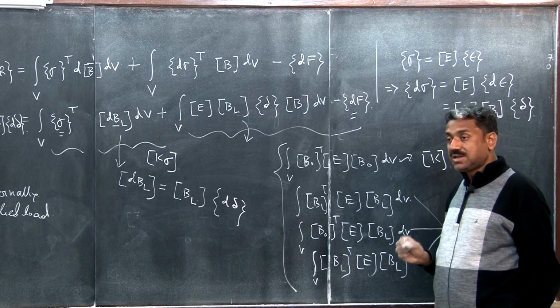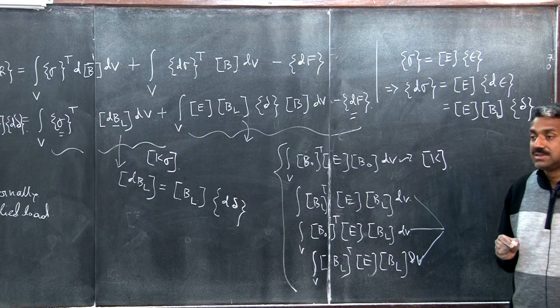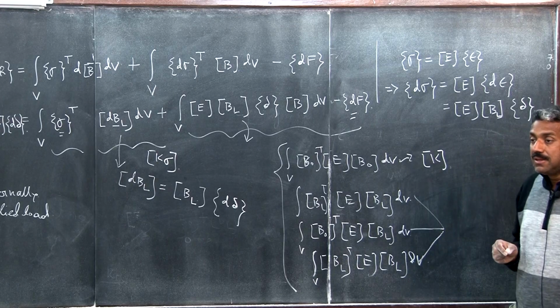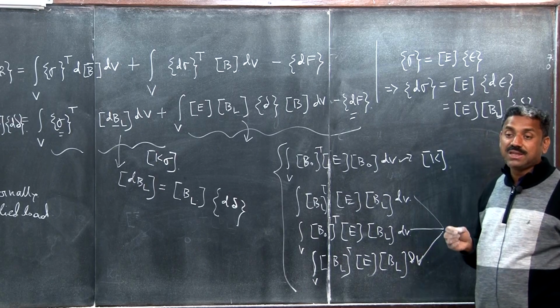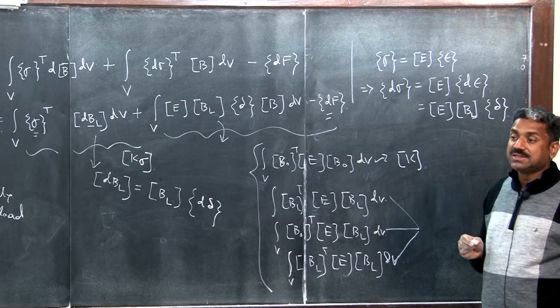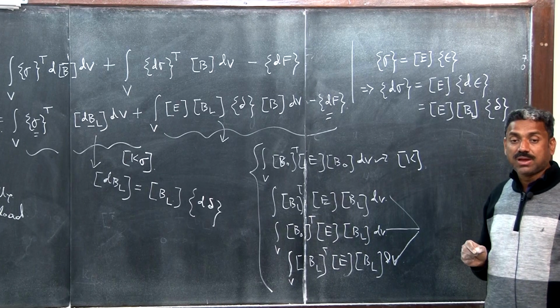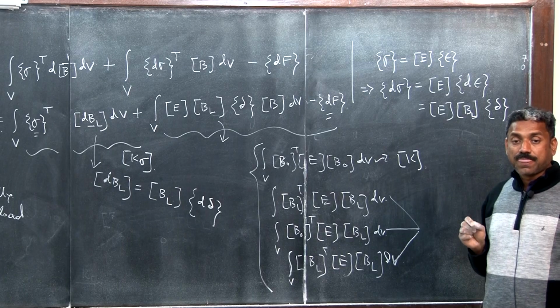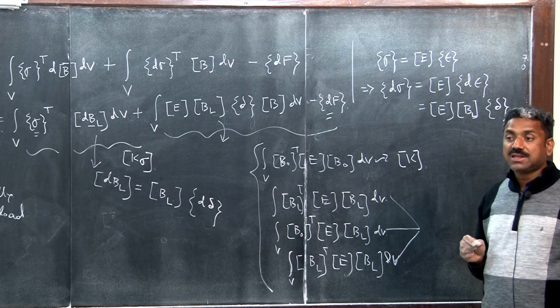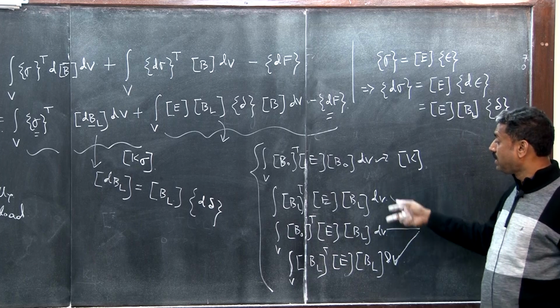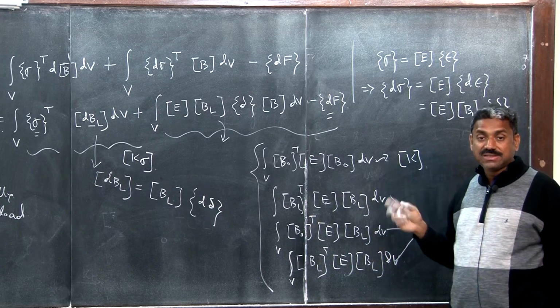So we must understand and appreciate the regime of analysis. How are we doing the analysis? We are basically doing a linearized analysis when we are solving the eigenvalue buckling problem. An eigenbuckling problem is basically a linearized stability analysis. But if you include the nonlinear term, then you will have additional stuff.